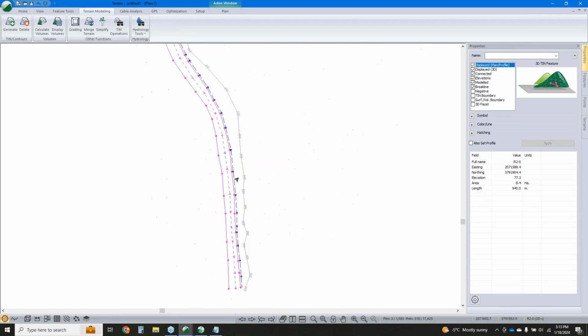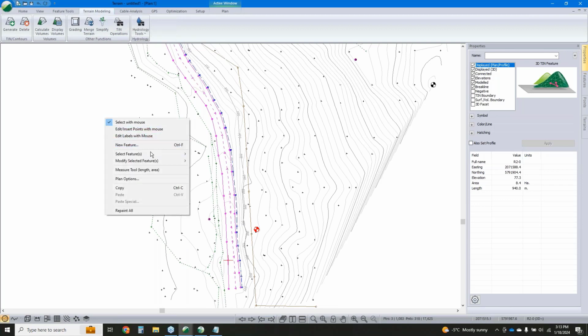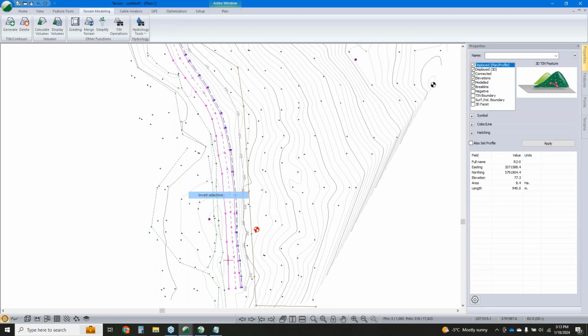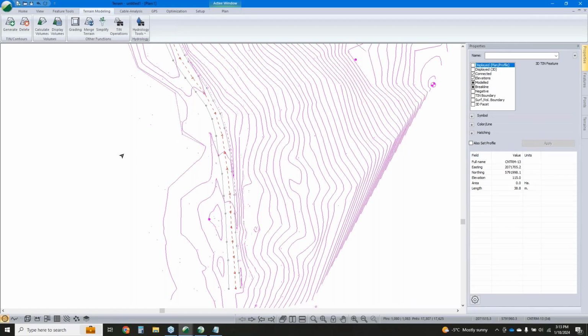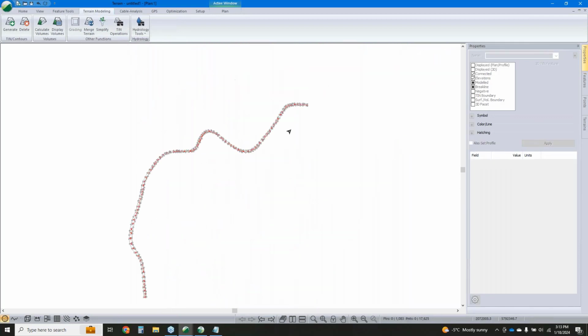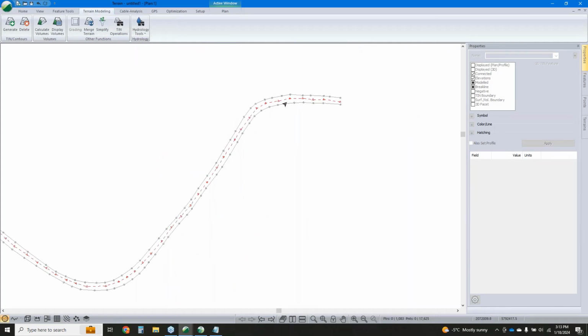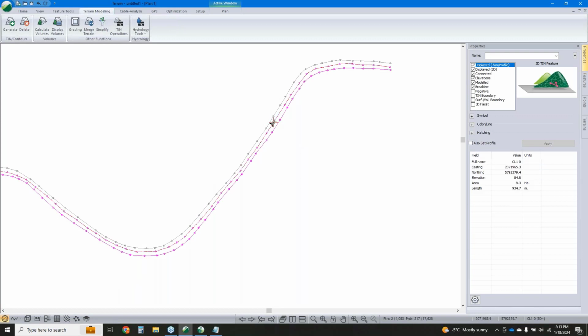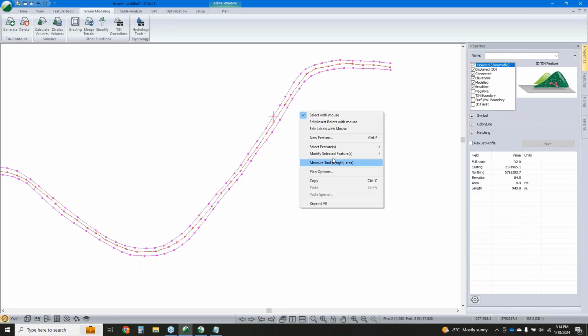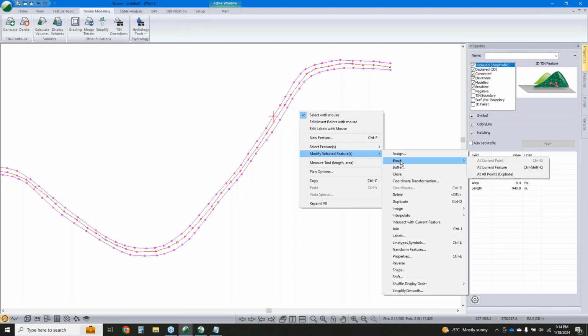In this case here, I'm going to just invert my selection. So everything that isn't the features that I had selected, I'm going to turn the display property off so I can make it really easy to focus on a certain type of point. And in this case, I'm going to just show something that's relatively common.